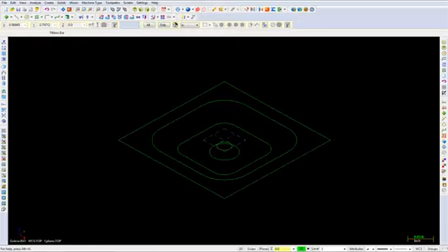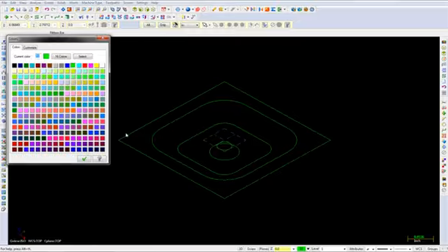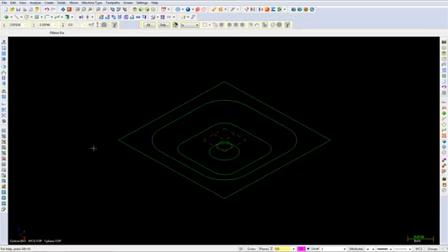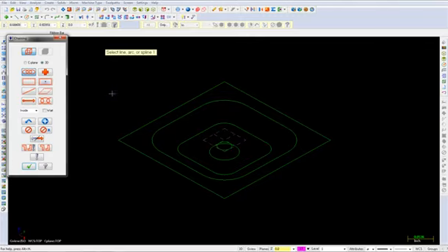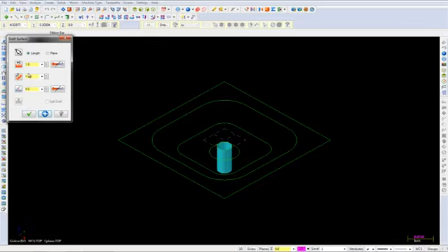geometry. Left click on Color here and change the color to magenta number 13. Select the OK button to exit the dialog box. Then choose the command Create Surface Draft. Select this arc here and choose the OK button to exit the chaining dialog box. Change the length to 0.25 inches and the angle to 10 degrees. Make sure that the surface is pointing downwards.